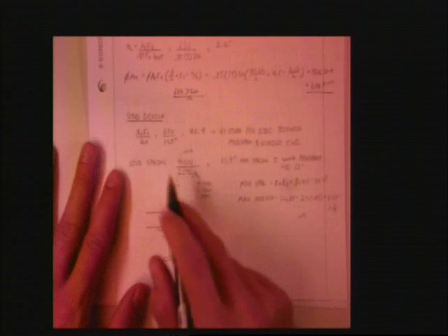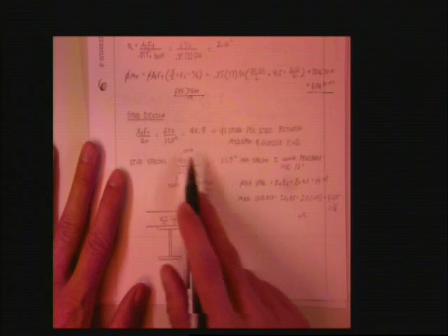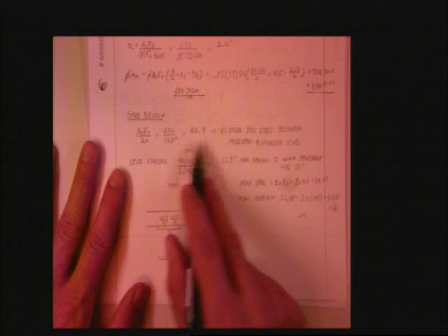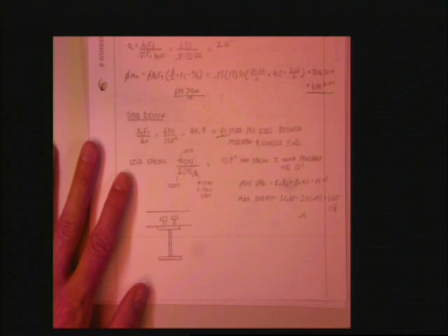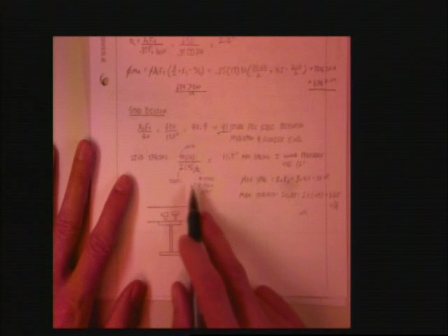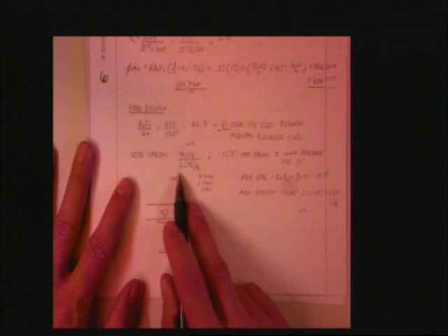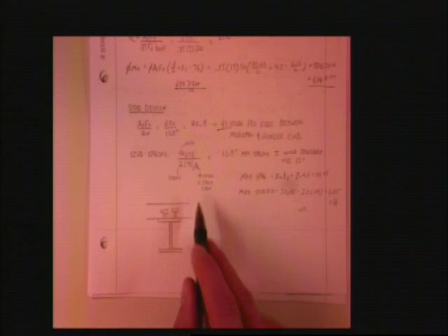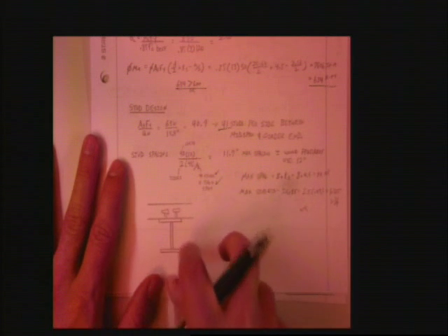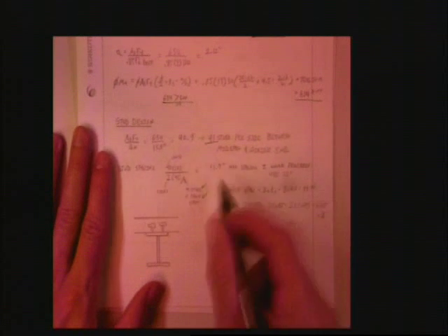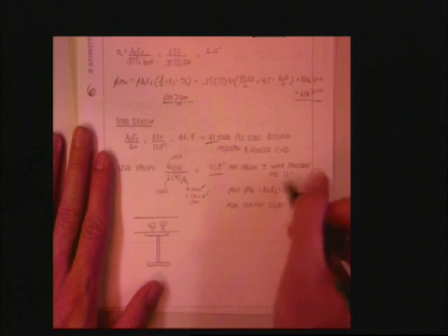Okay. So we do our stud design again, 650 kips divided by 15.9 kips per stud. We need 40.9 studs, or 41 studs per side between, again, where the maximum moment is. So I went ahead and did our stud spacing here. If our girder is 40 foot in length, dividing by 2 sides, dividing by 41, and I'm putting 2 studs at each spot, side by side, that means I can get away with 11.7 inch maximum spacing. So I prefer to go ahead and use 12 inches.